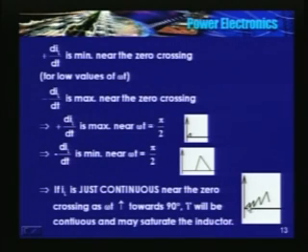Now what will happen as VO1 increases, mind you, from 0 to omega t is equal to pi by 2, VO1 increases sinusoidally. So the peak value of current also increases, but then as omega t increases towards pi by 2, it decays very slowly. Okay. So a small value of current, it has just touched 0 here. So definitely in the second cycle it will attain a much higher value than this, but then the rate of decay is slower here, so it will not touch 0.